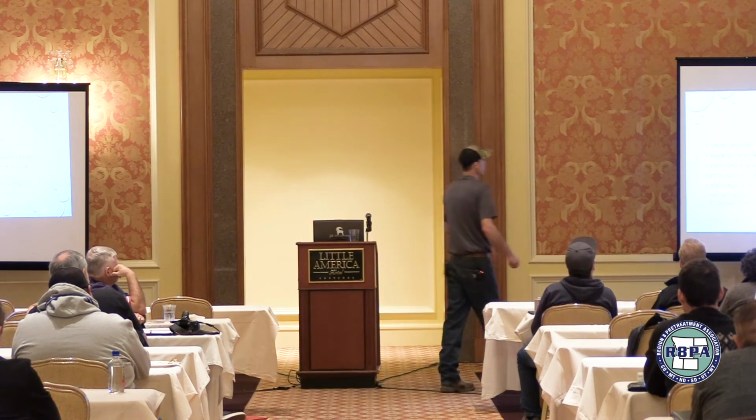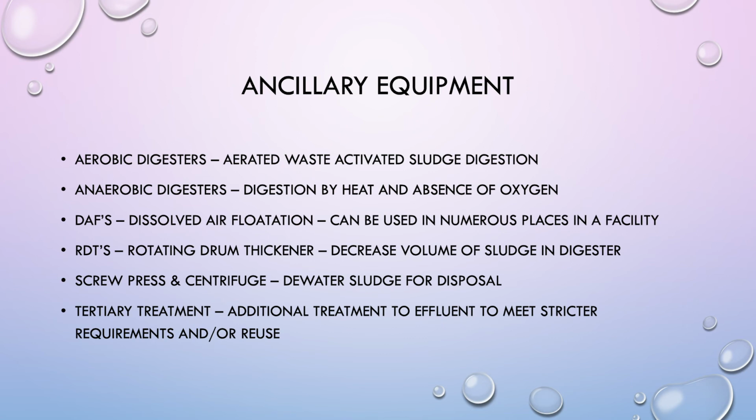Ancillary. I thought I'd be running out of time, so aerobic digesters we talked about. Anaerobic, those are those big dome-looking things with a lid. Heat and absence of oxygen, or anaerobic conditions, is how they do the volatile solids reduction. DAF, if you guys have worked in the pretreatment world long enough, I'm sure you've seen a DAF at a pretreatment, at a categorical industrial user or significant.